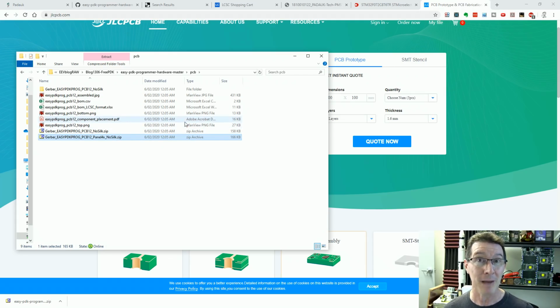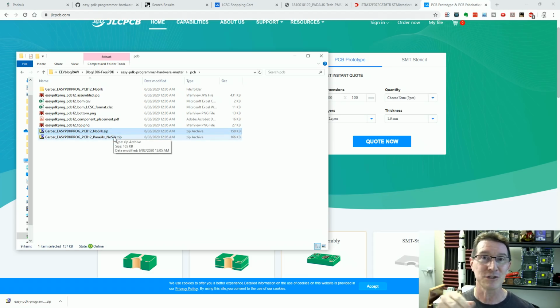We can manufacture the panel for you, but it's going to cost a lot more because it has to go through its own separate process. So yeah, don't do that. You can order four of them, but just say I don't want silkscreen, and then they get all confused and come back to you with questions. Oh, do you really want V-scoring? If you do, how do you want us to route it out? But they're too close to add routing paths and stuff. Oh, it's just no. Get your individual one-off boards made.